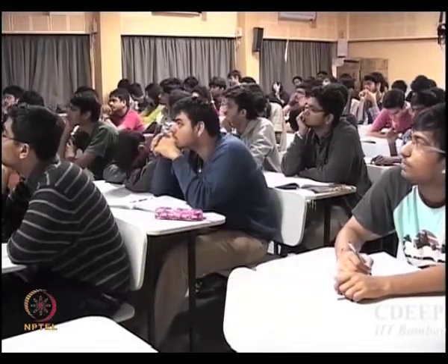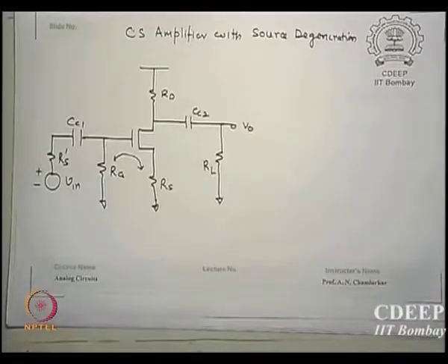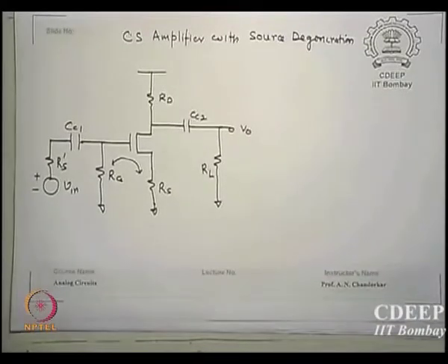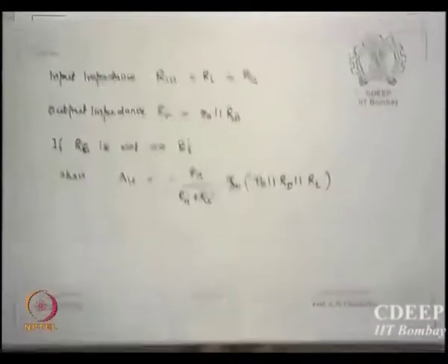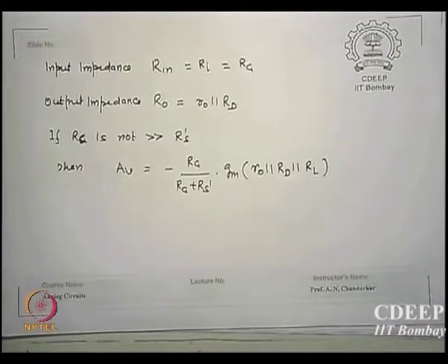There is another common source amplifier which is very popular. Okay, before we quit here, in this equation you can see here, R0 is equal to how much? 1 upon lambda ID. Is that correct? Lambda is what parameter we call? Technology. This is decided by the technology.